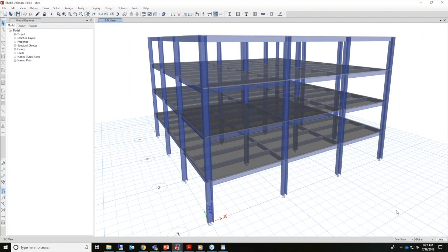In the first model, we defined an acceleration and applied it to the structure. What we're going to do here is apply a load in a load pattern and then generate a blast function. I'll show you how to do that. So first of all, I'm going to select this joint here. This is the point where the blast load is going to be applied. So what we need to do here is first assign a joint load, which I've already done, but let me just go through the steps.